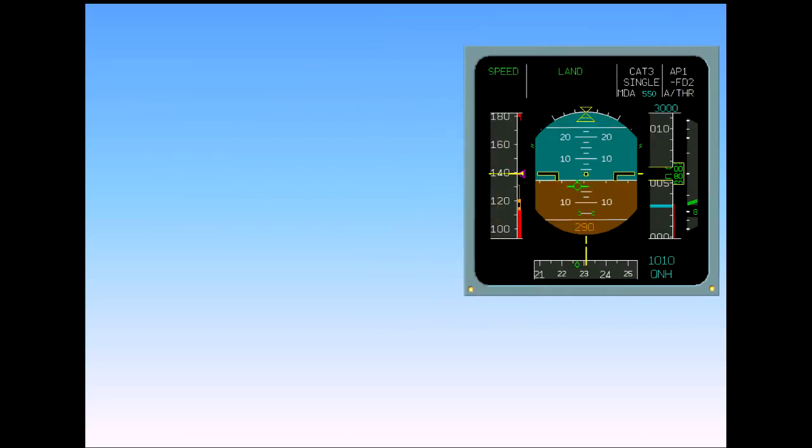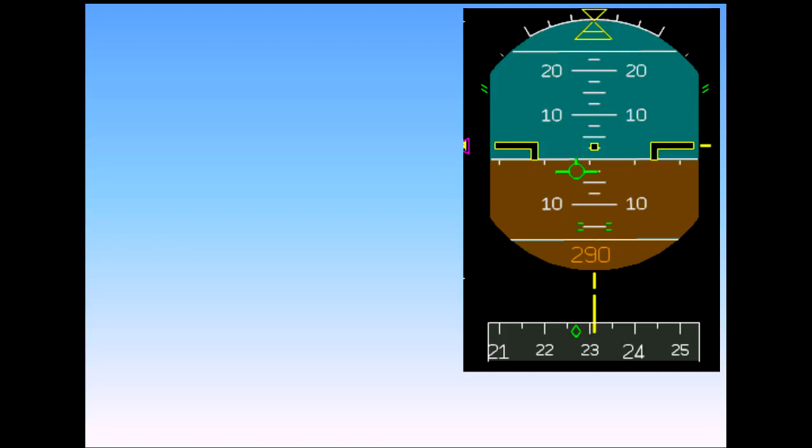The flight path vector can be displayed on the PFD to show you what the aircraft is doing in relation to the world. It is an indication of the aircraft flight path. It is not a director. The green symbol, sometimes called the bird, represents the aircraft. The attitude indicator represents the world. Let's look at the FPV in a bit more detail.